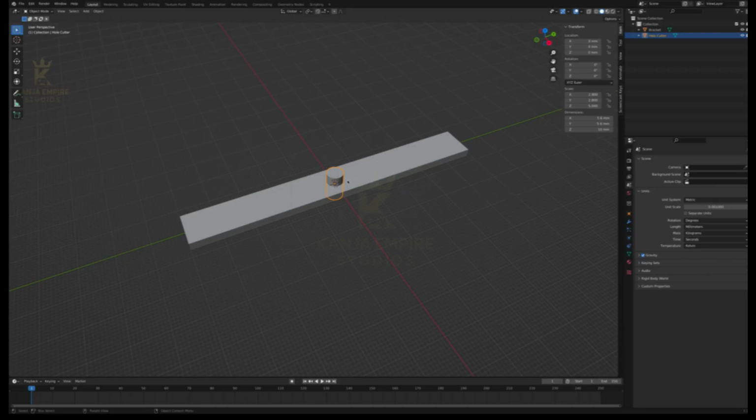And actually, how many holes do we want first off? Let's say we just want 3 holes, kind of evenly spaced. Well, we'll need to duplicate the hole cutter 3 times, and it's just a cylinder, I'm just calling it the hole cutter. Just right click on it and go to duplicate object, and then I'll just press escape so that way it doesn't change the position of it.